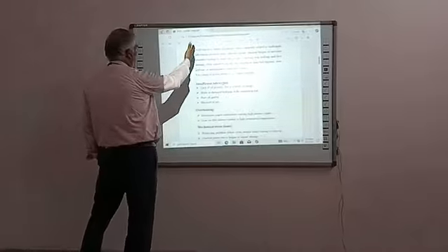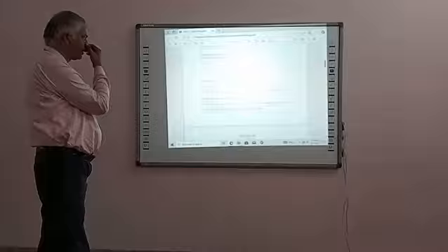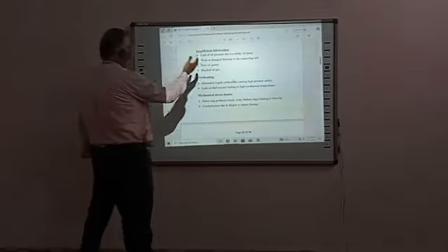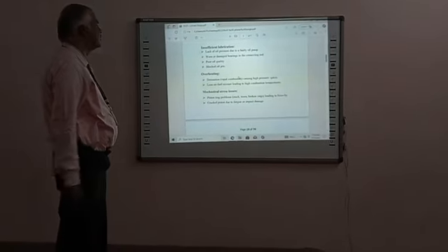These are some of the reasons for piston failure: lack of oil pressure due to a faulty oil pump, burnout, damaged bearings, poor oil quality, blocked oil jets.